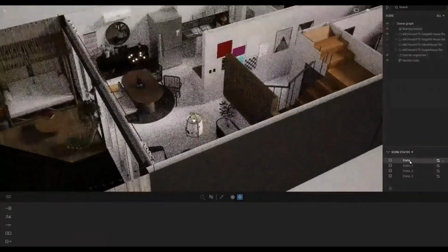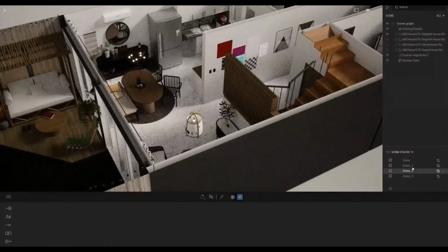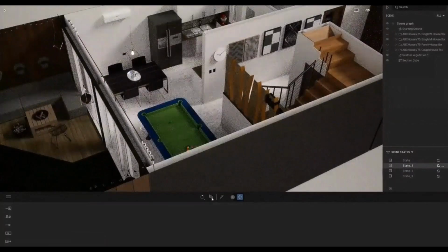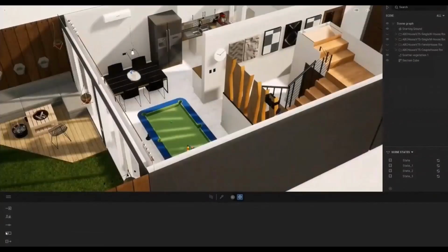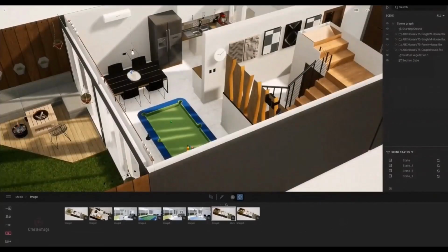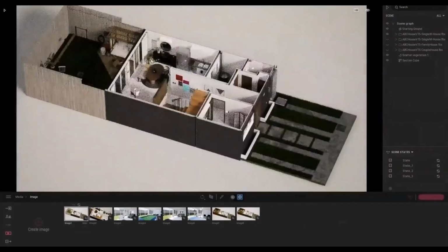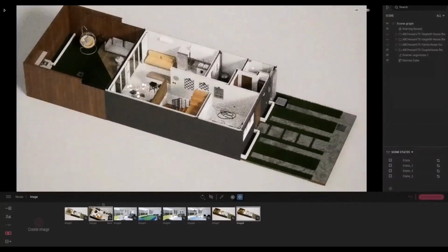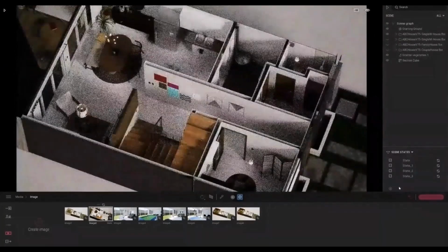And then we can switch the path tracer on to have a look at how each one of those looks, or how it renders. Okay, we can switch it off so that we can come in to raster mode and we can look at the images that we did create. So we can cycle through the different images that we've got. And I think these are all set to high quality. So we just need to come in and change it to low.